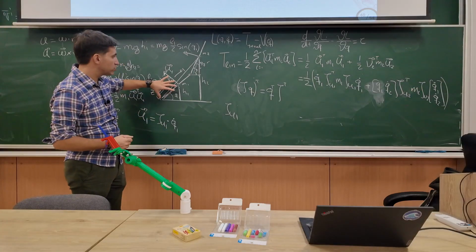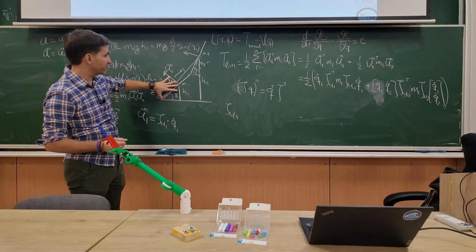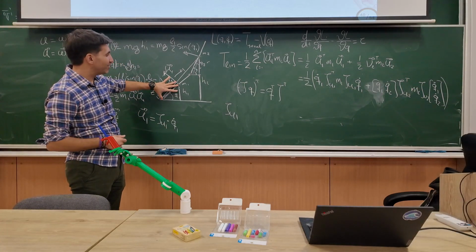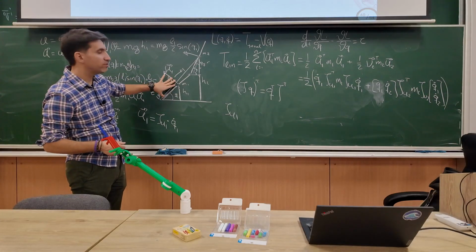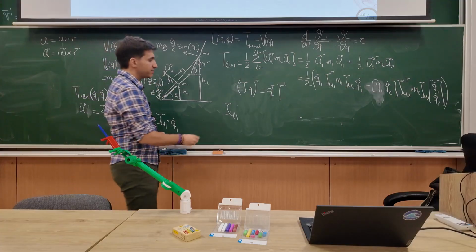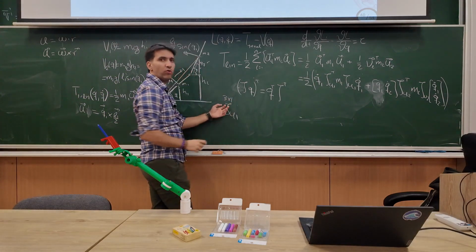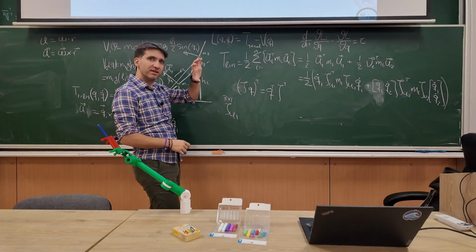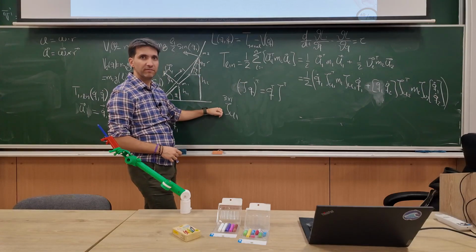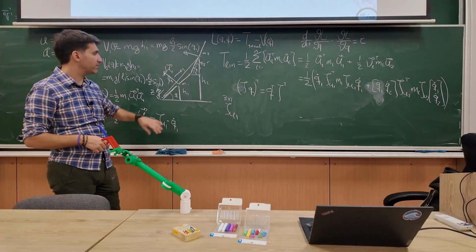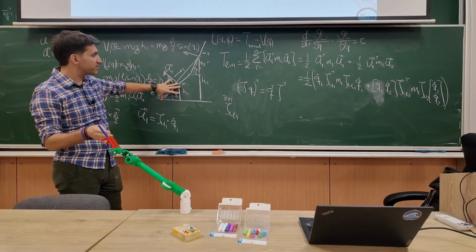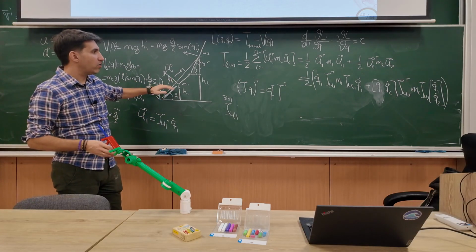So the second part is correct, the first not. But the logic is fine. We're only until here, so we have only one joint involved, so we have just one column. It's 3 by 1 because it's the linear Jacobian, not the angular Jacobian. So we would just have the linear velocity part, it's half of the Jacobian. The difficult part is realizing that this is a one-column one.